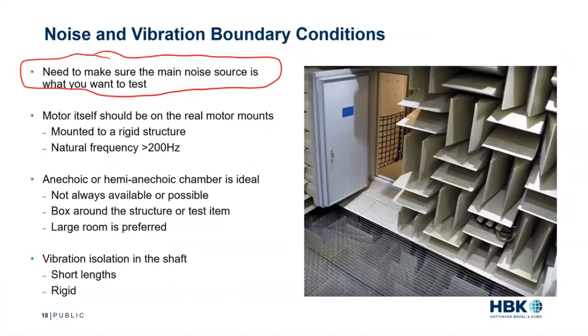And Ed Green and myself from some previous jobs we've done together, this becomes critically important because there are so many noise sources, and even if you're looking at the machine itself and you want to compare inverter noise and machine noise, you need to make sure you have those decoupled. So a lot of times we end up putting or desiring to put these tests in an anechoic or hemi-anechoic chamber, and I'll touch on that in a moment.